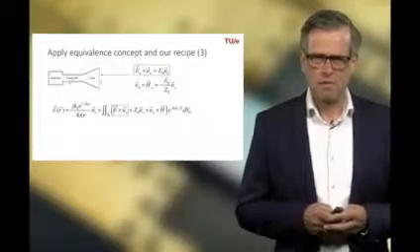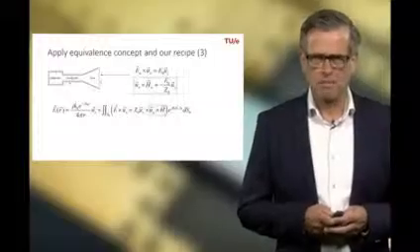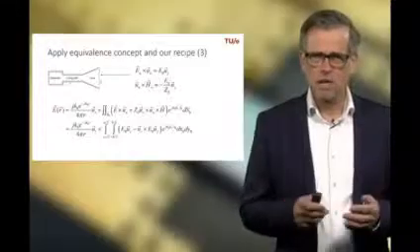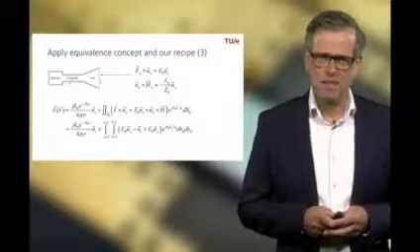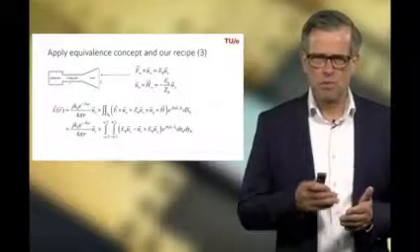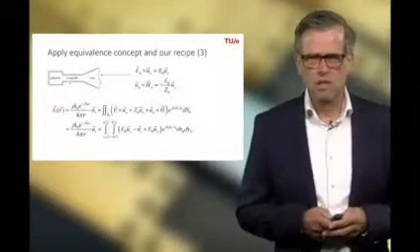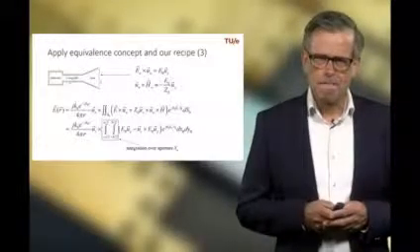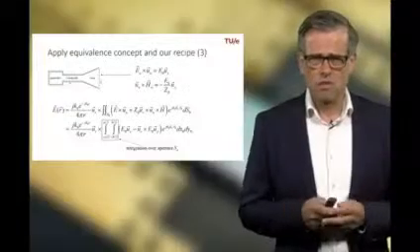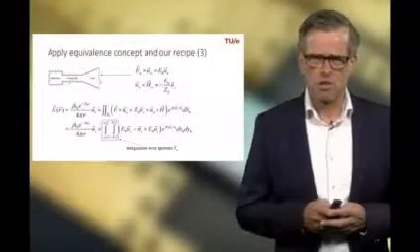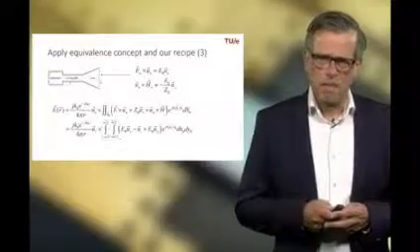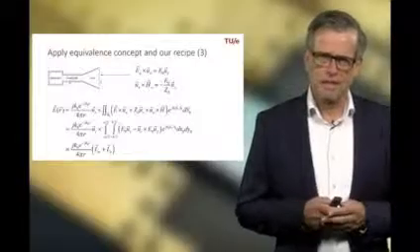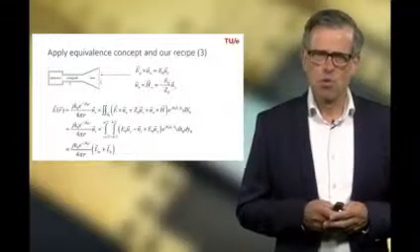If we do that, with the electric tangential field and magnetic tangential field, we arrive at this expression where we need to integrate over the surface SA, so from minus A over 2 to plus A over 2 and minus B over 2 to B over 2. This integration is not so difficult to do, and we will show that in a second. It is convenient to split the integral over two integrals, LM and LE, and we're going to work out both integrals in more detail.